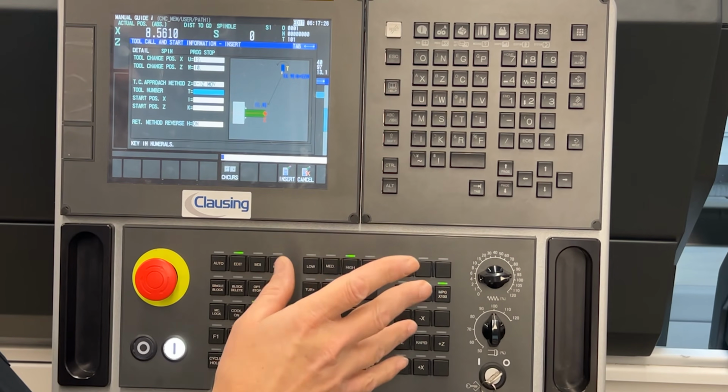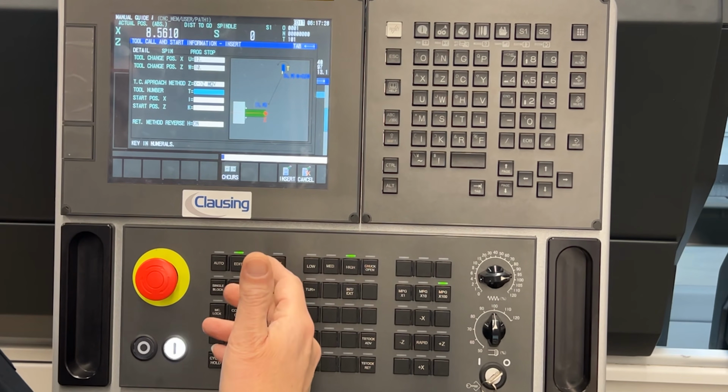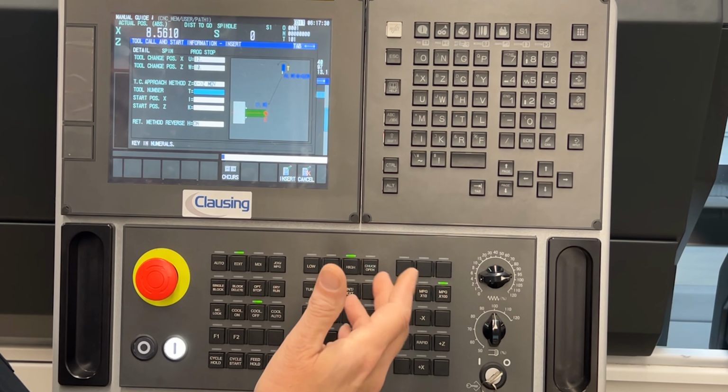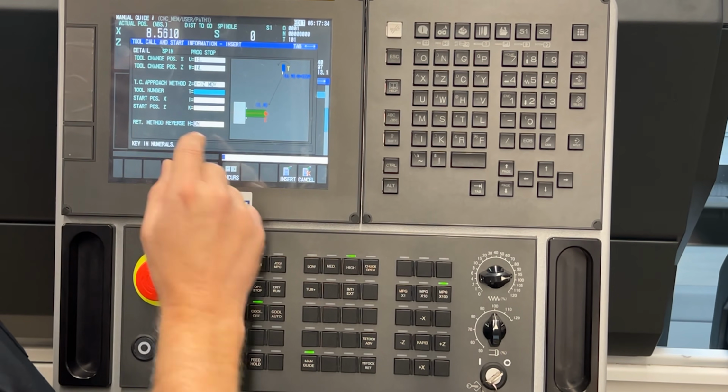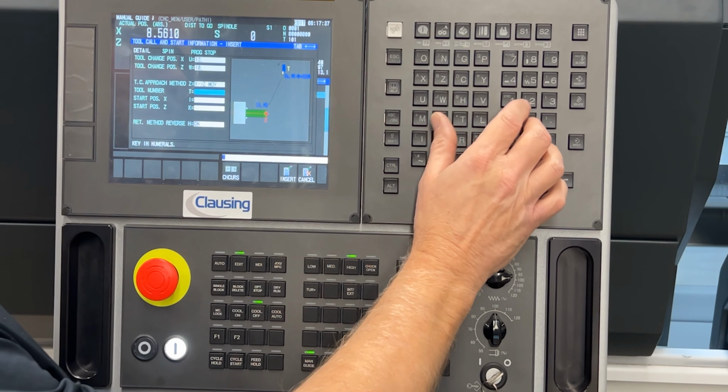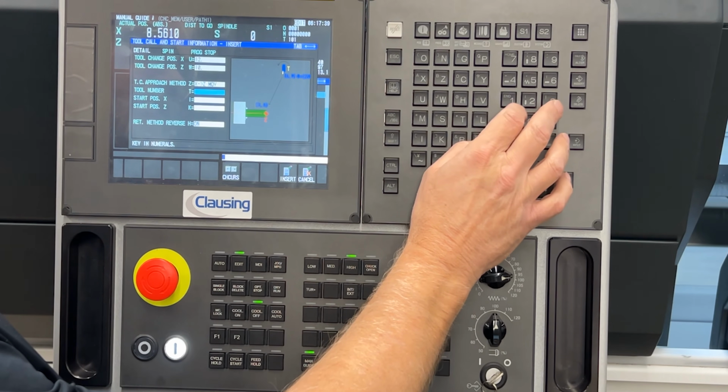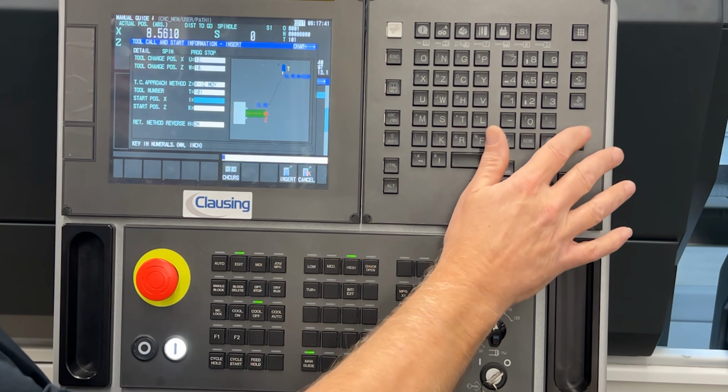Once it gets there, it's going to stop, which is going to shut the spindle off and everything, so you can open up the doors, and for a tool post you can change the tool. In here, I'm going to put in what tool I'm going to grab or change it to. So I'm going to put in there 101 for tool number 1.